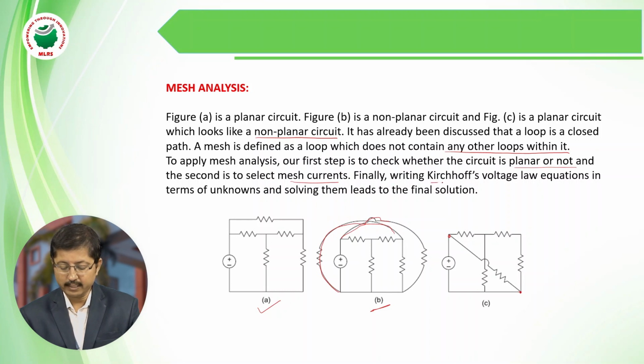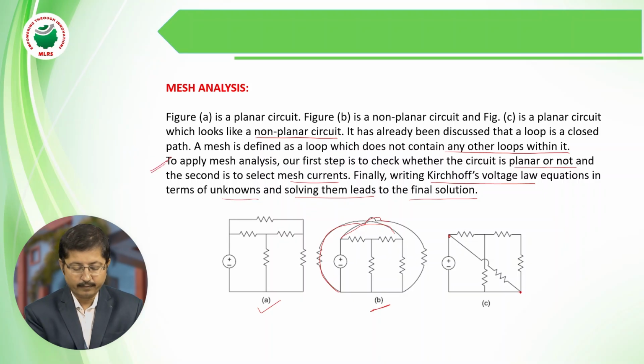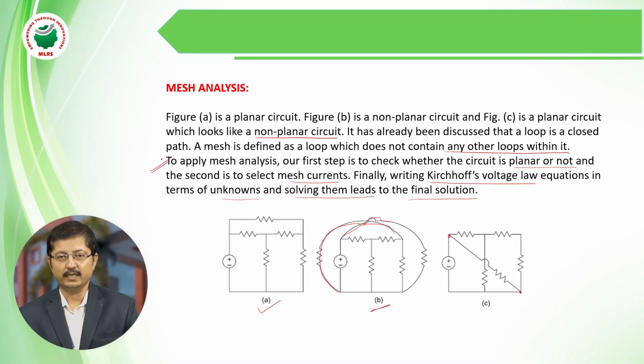Finally, write the Kirchhoff voltage law equations in terms of unknowns and solve them, which leads to the final solution. So these are the steps for applying the mesh analysis. Once more, what is the first point here? First we have to check whether the circuit is planar or not.